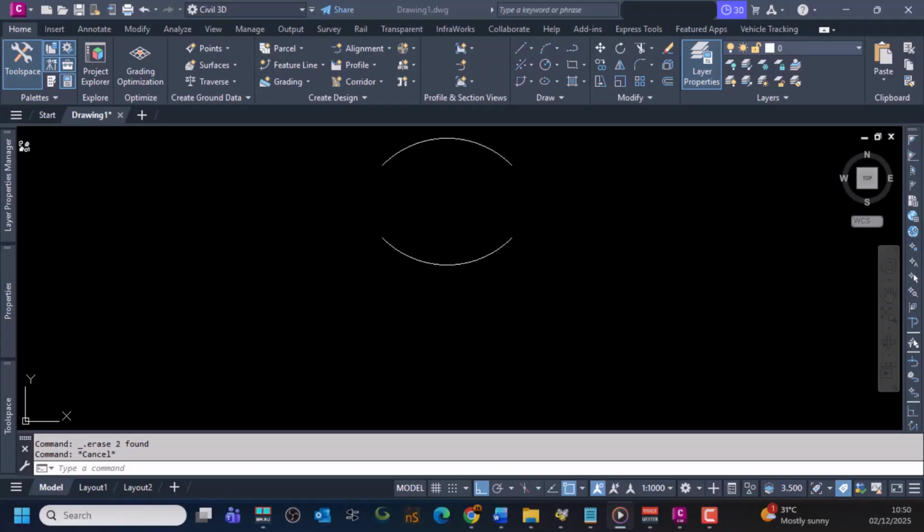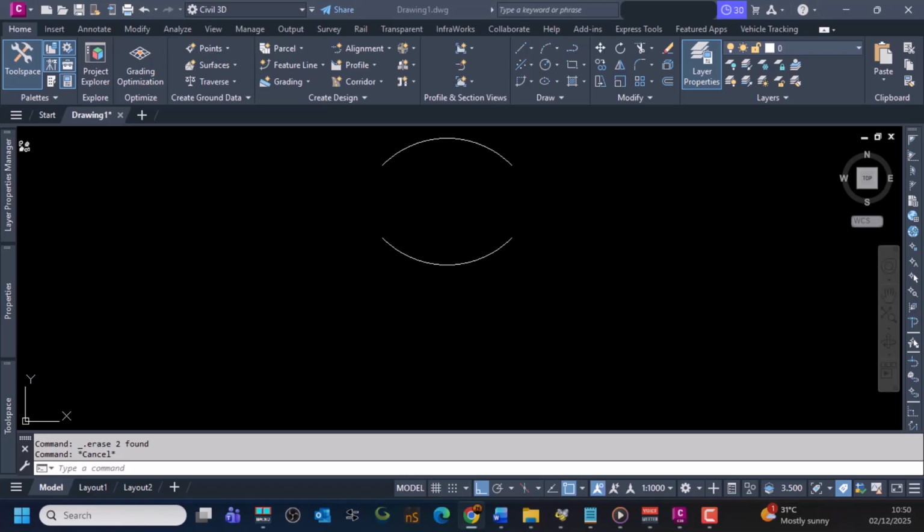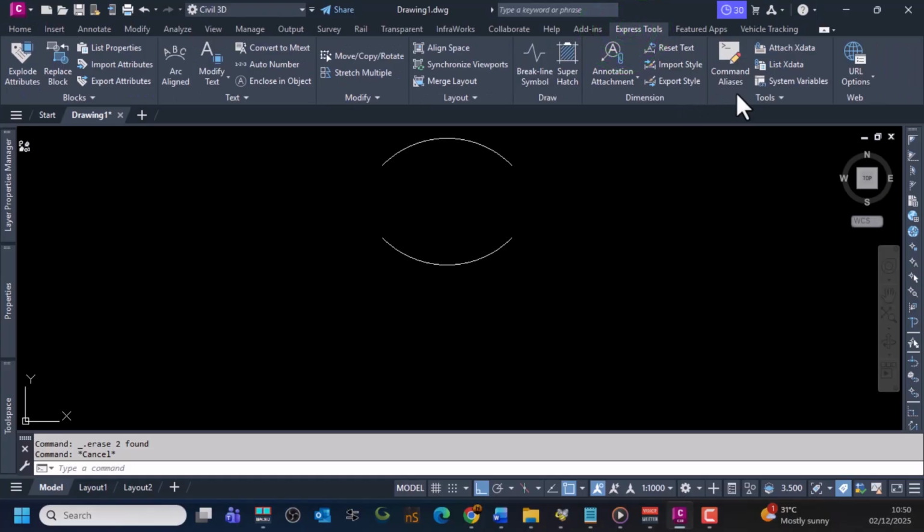The second method of line type creation doesn't require you to create your own line type definition in the acad.lin file, but does require AutoCAD Express Tools to be installed. On the Express Tools tab of the ribbon, expand the Tools panel to find the Make Linetype and Make Shape buttons. The advantage to using the Express Tools method is that it allows you to easily create shapes and incorporate these into your line types. To incorporate geometry into the line type other than text, dashes, and dots, it will need to be included as a shape object, which the MKLTYPE command will be able to recognize.